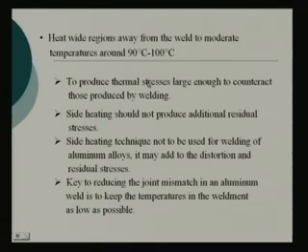The whole idea is to counteract the stresses which may form by the welding. The second point, obviously, one should be careful that it does not add to the distortions. And in the case of aluminum alloy, such a technique is better not to be used, because it may add to the distortion residuals, because that is a highly conducting material.